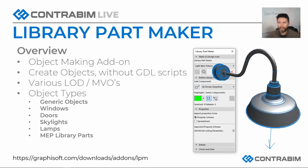So yeah, what is the library part maker? Well, it is an add-on that has been available for Archicad for a few versions now. Really what it enables us to do is create objects without the need of GDL scripting. Now we've always been able to model and create objects just by simply doing save as object type. But what's great about the library part maker is it allows us to add different levels of detail so that when we toggle different model view options, we can associate those levels of detail with whatever level we want to represent, whether it's in 2D or 3D. So that's one of the great features of the library part maker. We can create really any type of generic object. We can also create windows, doors, skylights, lamps as well, and a wide range of different MEP library parts.